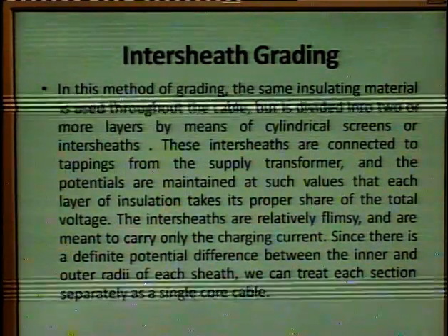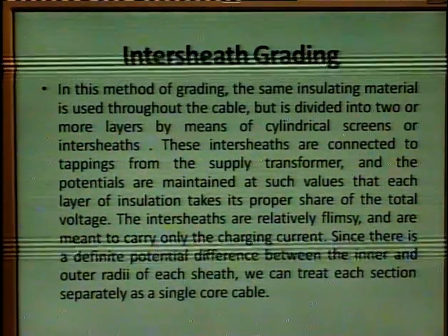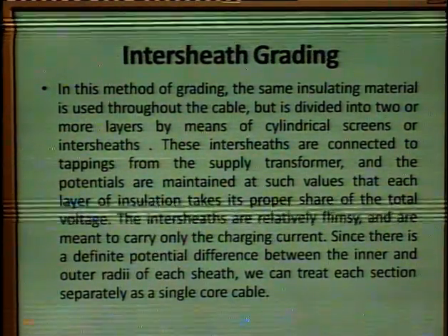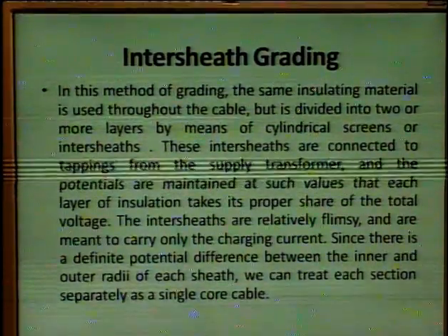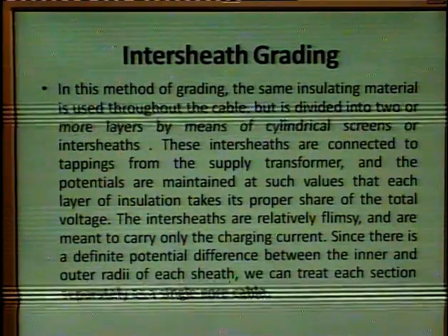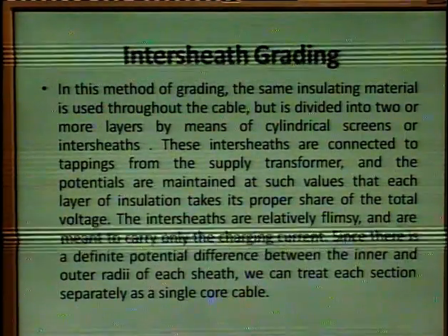Then we have the intersheath grading. In this method of grading, the same insulating material is used throughout the cable, but it is divided into 2 or more layers by means of cylindrical screens or intersheaths.